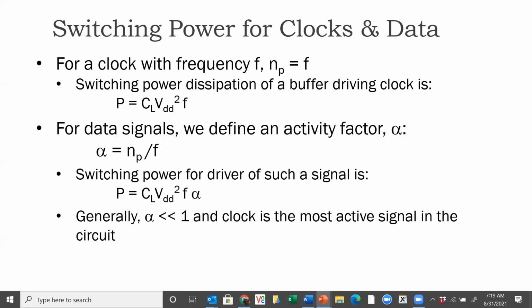So even though supply voltage reduction can reduce power, it comes at the cost of reduced clock frequency or reduced performance, since all the delays increase. Clock frequency can be decreased if it is possible, but sometimes that is not possible because we want a very high clock frequency for the performance we need from a chip. And then the activity factor is the final thing that we can try to reduce.